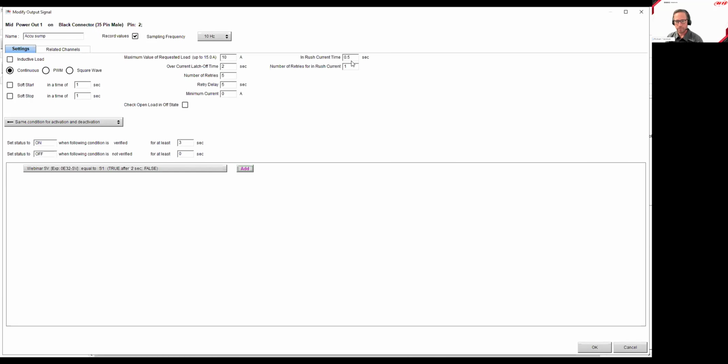So if you think of a fan that's stationary, it has to get moving, and the amount of current that we have to supply to the fan is increased substantially. So in this, I can program the fuse of the first activation event for a different value than my programmable fuse. And when the fan is running, I know that it runs at 16 amps. But when I first turn it on,